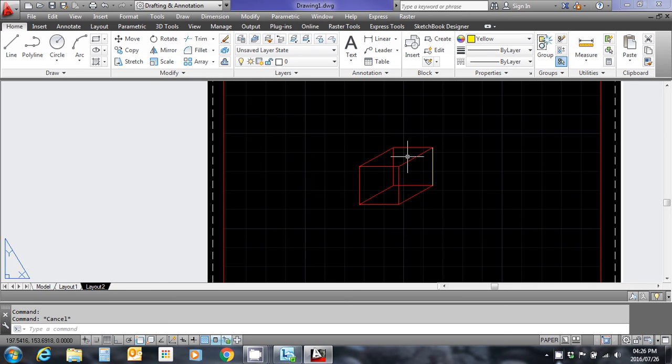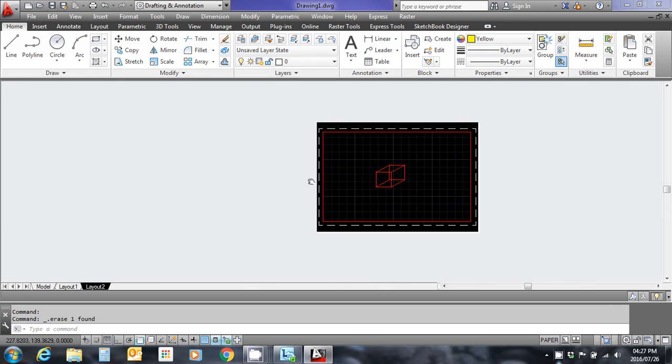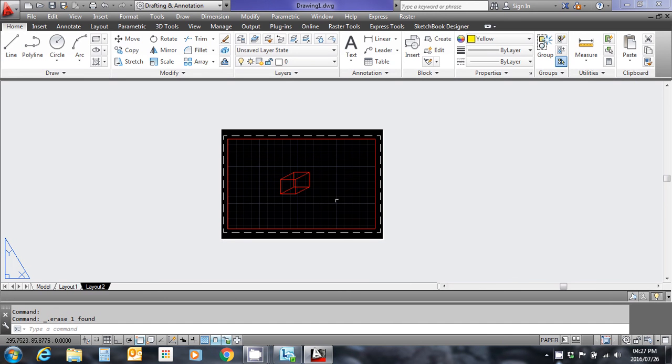Good. Well, am I ready to print? Well, let me first delete this line that I created in paper space. I now have my page set up. You would typically have a title block, north arrow, all the bits and notes that you would need, the rest of the drawing as it would have been drawn. Let me now try and print this drawing by using the PDF printer.